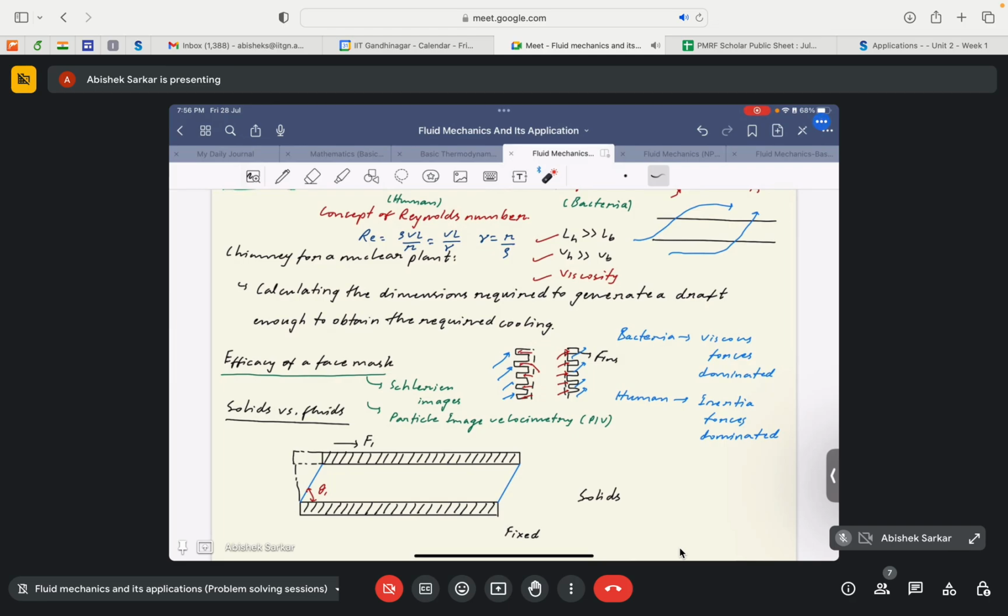It is conduction. And if there was no motion of fluid, right, if the bike was stationary and the engine was running, then also there would have been heat dissipation. How? It would be through conduction, right? There is a temperature difference between the outer surface of the fin and the ambient air. So this will result in a diffusion, a conduction between the outer surface of the fin and the air, right? But I said that since the air is moving, the convection would dominate, and thus the dominant mode of heat transfer in this case would be convection.